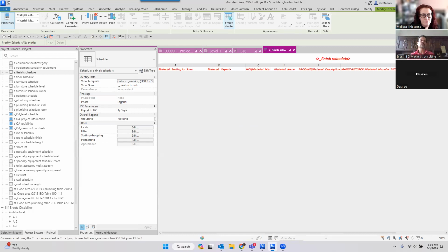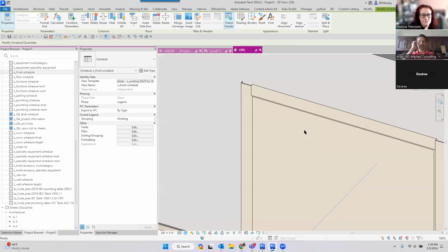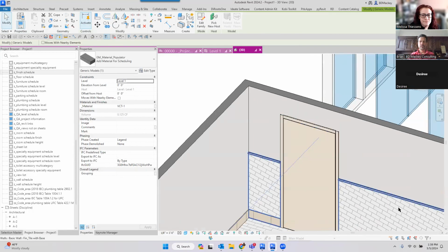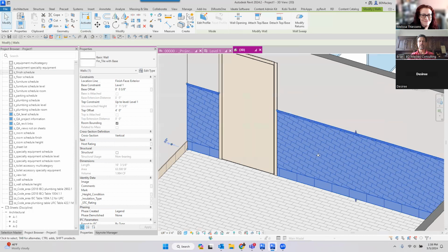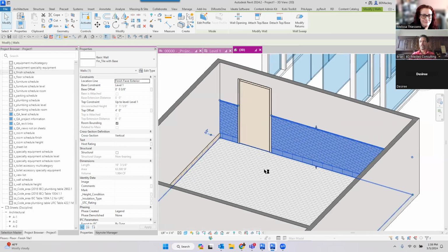So like I said, I do use material as paint in the family environment. I just almost never use it in the project environment because inevitably in a project, somebody's like, well, I changed this wall from tile to wood and it's still showing up as tile because somebody painted tile over tile or something stupid. I literally had one client, a new kid went in and painted all the materials in an entire room, and somebody's like, okay, now you've got to switch those floors. And so we had to go remove all the paint. Yeah, it was a big deal.